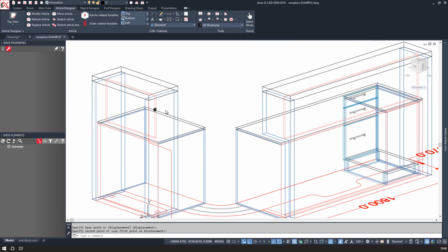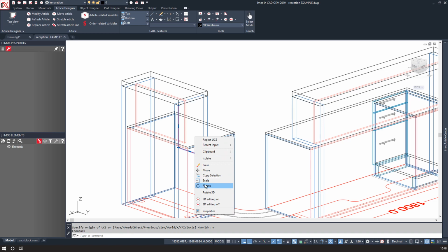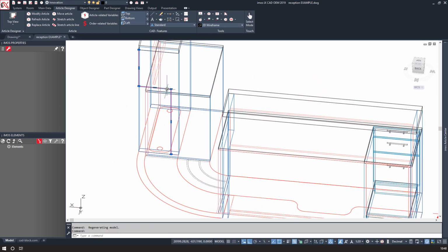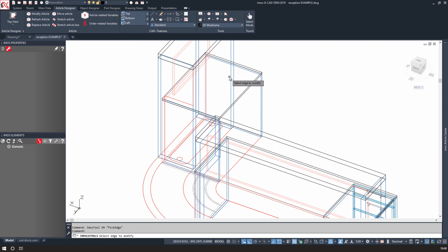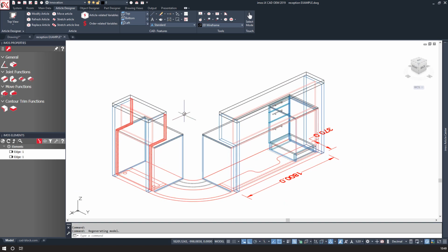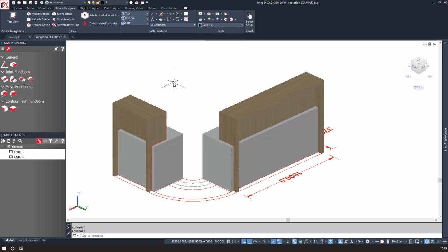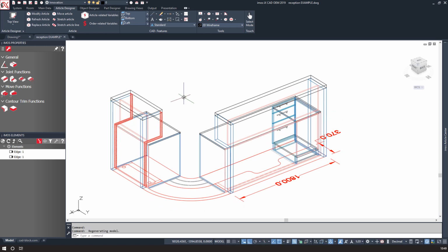I can then use the same polyline and I'll just copy and rotate this. Let me just rotate. Okay, this looks better. Nope, yes, that's the wrong way around, so I need to rotate that again. There we go. I'll just move this back into the correct position. And if I just select the edges, I can do the same modification. Okay, this looks good. Let's switch into a realistic view. Yes, I'm happy with this, I think.